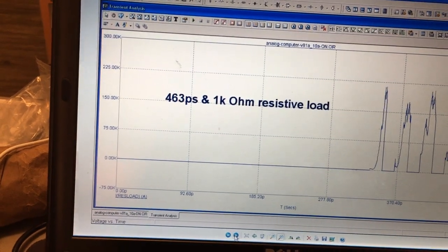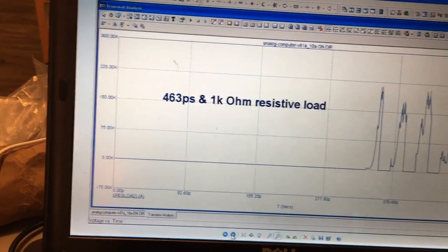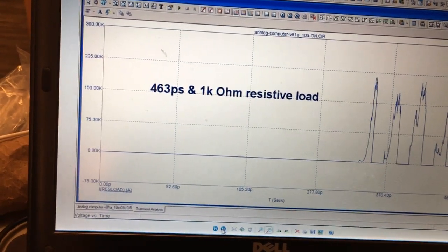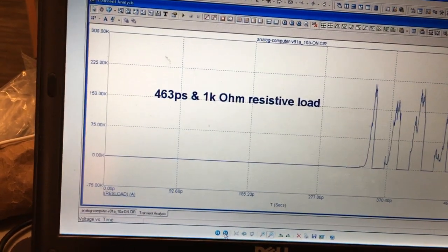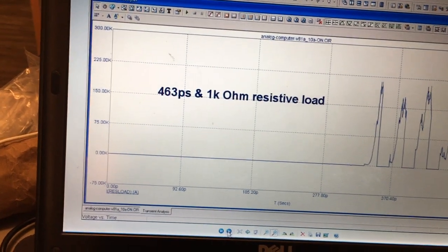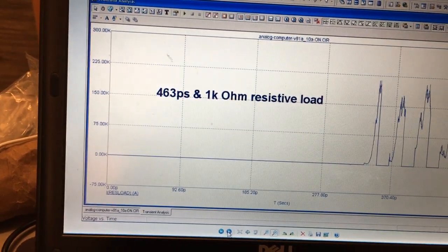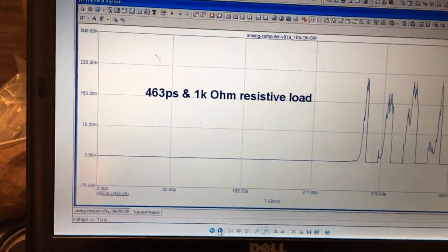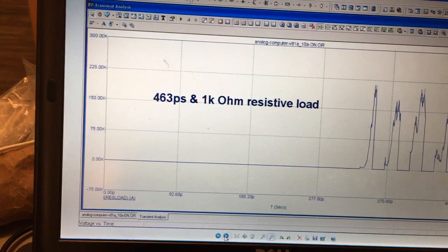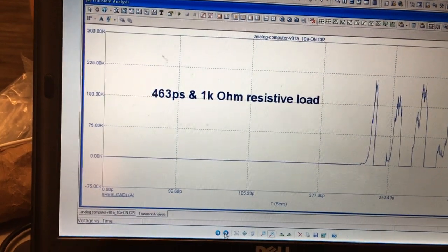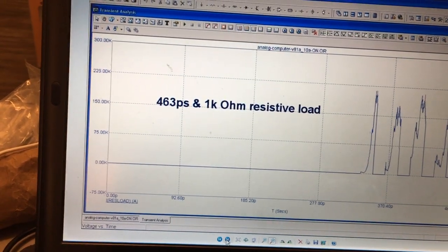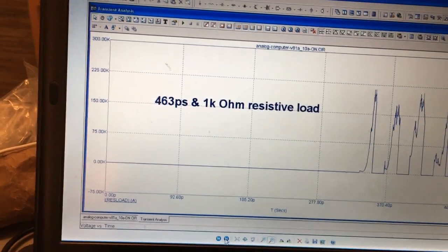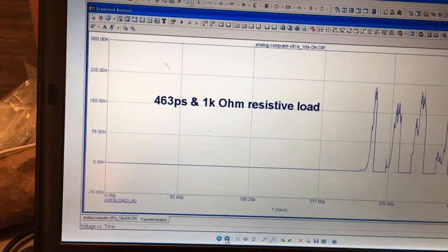And yet the very nature of this overunity phenomenon is divergence. And so it's not a fault of the simulator that it can't handle it. So that doesn't mean matrix is singular is a fatal error in the real world. Yet, that's where I diverged. Yet, it does mean the circuit is probably so stressed that it may not be able to hold itself together and come up with consistent results. If the simulator can't come up with consistent results, why should the circuit?